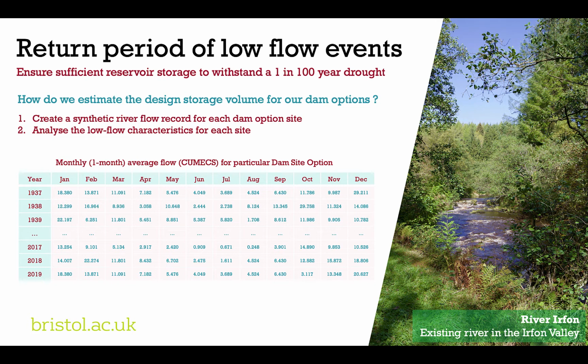The way we do that, I'm going to illustrate using the data in this table below. So the important thing when you're designing your dam storage is that you need a suitable time step at which to consider the flow volume that's available, and we're going to use a monthly time step here. So as you can see in this data table, I've tabulated data for a number of different years, and I've done that for each of the months. Now the data inside the table is completely made up, so it doesn't really bear any relation to your project. It's purely indicative so that I can illustrate what you need to do.